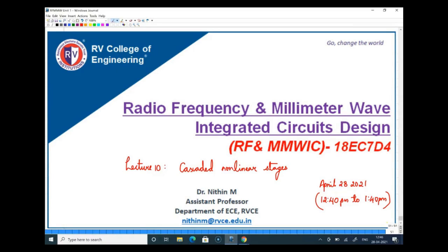We arrived at two specific performance metrics or performance parameters. One is the 1 dB compression point, and another one is the third intercept point or IP3. And I hope you understand why we have these two performance metrics. The 1 dB compression point tells us something about the linearity of the circuit, and IP3 is basically to understand how much the third order intermodulation product can be.